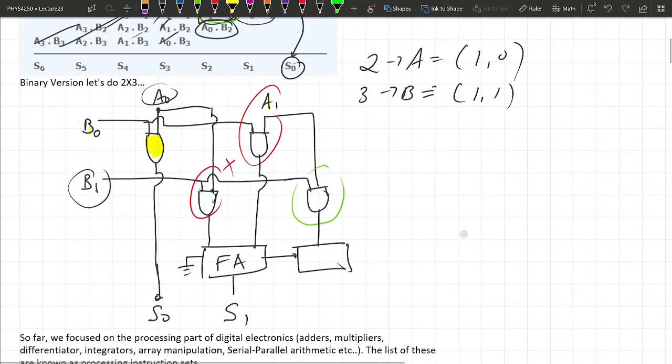So in general, what will happen is that you'll keep adding these AND gates until you run out of AND gates, until you run out of bits. But since we know it's always going to be 0, we can connect that to ground, because ground is equivalent to 0 in digital logic. And then the result of this will give us whatever S2 is going to be.